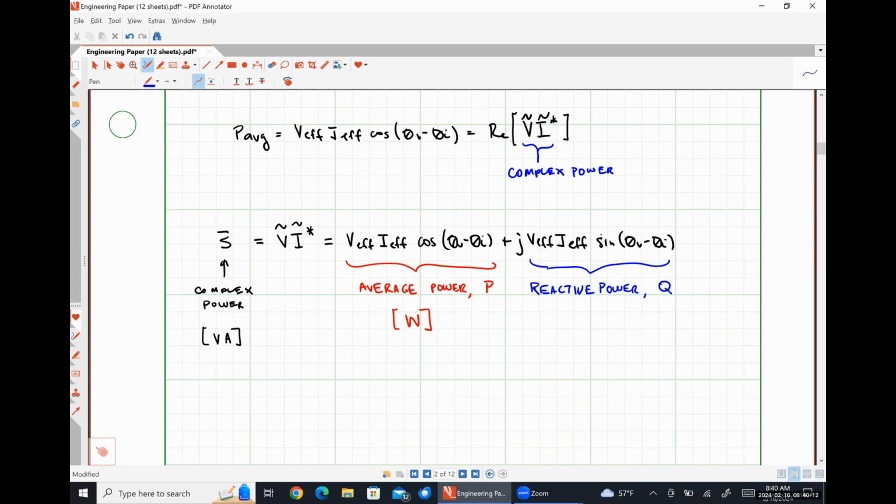Okay? So when we were looking at the instantaneous values for our power last class meeting, we saw that the average value of the instantaneous power absorbed by a capacitor or an inductor was 0, which means exactly half of the time those elements were absorbing power, and exactly half of the time those elements were supplying power back to the source. So they are inherently temporary energy storage. They're constantly taking energy in and releasing it back out.